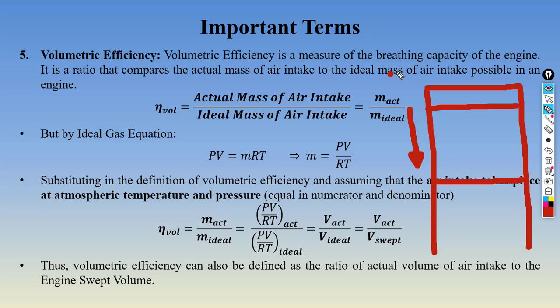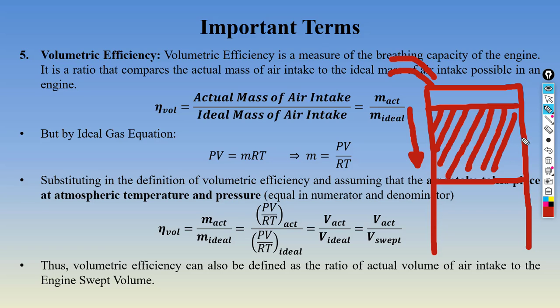What do you expect? You expect that all this amount of volume should be filled up with the incoming air. Whatever air is coming into the engine, that air should fill up all this volume. What is this volume? This volume between top dead center and bottom dead center is your swept volume. Ideally, all this volume should be filled up by incoming air.